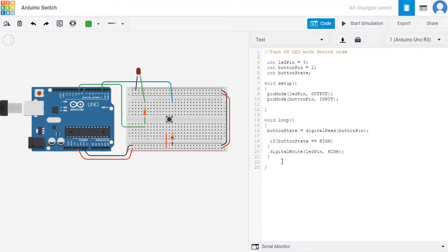And then we have to write the code that will allow us to deactivate an LED when we switch off the button. From here, you can see that if the button state is low, this means that if our button is deactivated, therefore our LED should also be deactivated. And we have to write a short time delay at the end of our code.